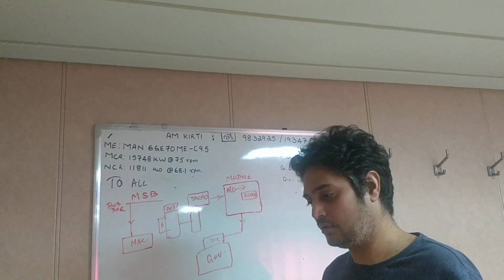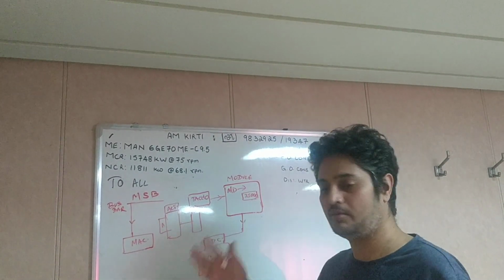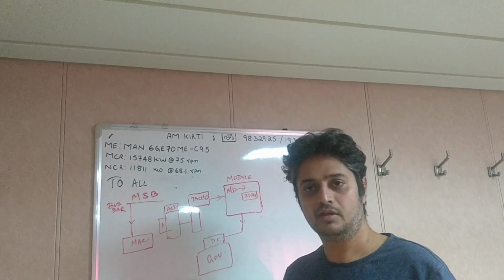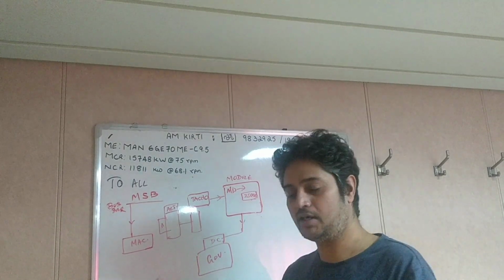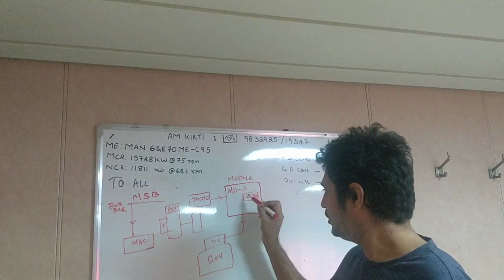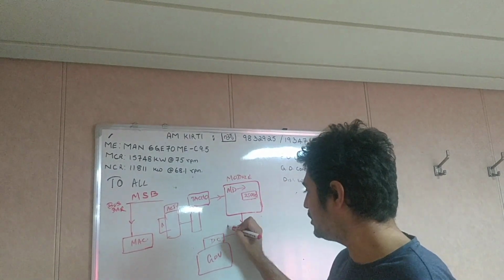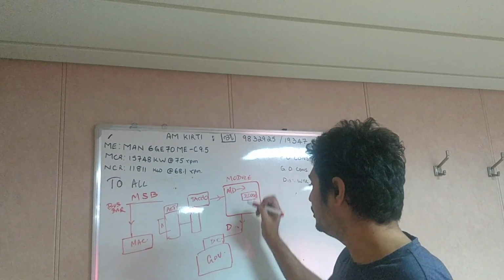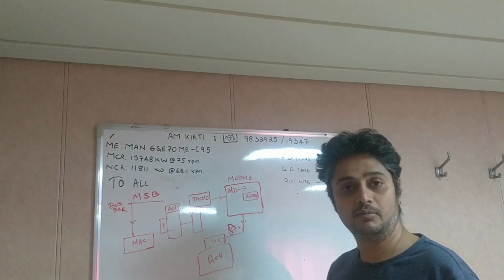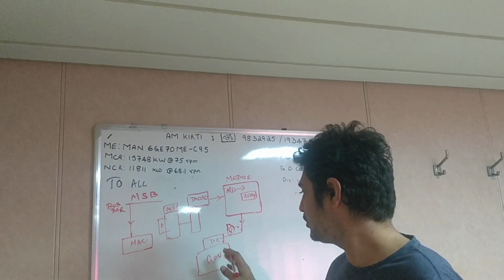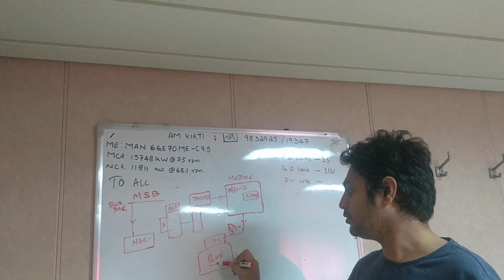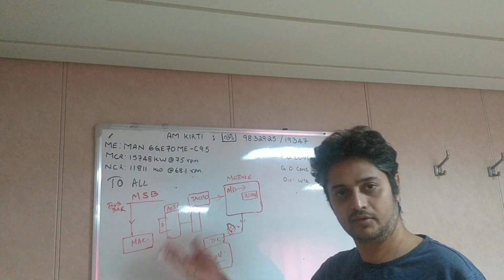So you would have wondered, if the RPM is dropping, how is the governor taking care? Everybody will tell you the function of the governor is to maintain the constant RPM of the prime mover. But how it is doing it is, this PLC module will give a digital signal, basically a voltage signal, to the governor motor. The governor motor is usually a DC motor. So this will give a voltage signal to the motor and tell it to increase.